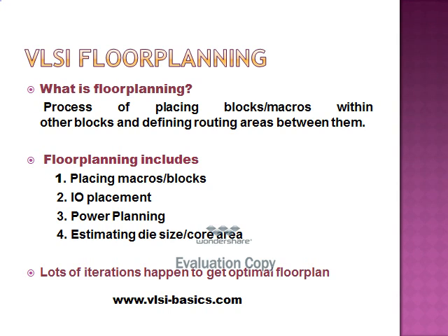The decisions taken for macro, block placement, IO pad placement and power planning directly or indirectly impact the overall implementation cycle. Lots of iterations happen to get an optimum floor plan. A good floor plan should make the design routable, improve the performance and minimize the chip area.